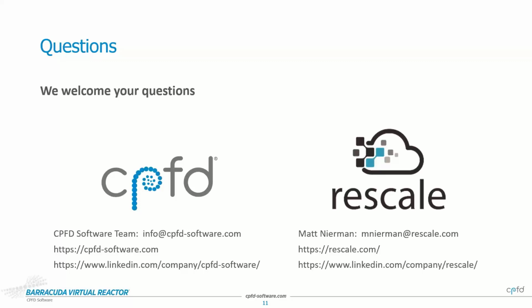Can I use Rescale or use the cloud alongside my on-premise hardware? Yes, absolutely. As we learned today, you can prepare your jobs on your on-prem hardware, and then when you're ready to submit a large job, you can do it through the Rescale cloud. It's really just a web browser portal kind of thing. Upload files, everyone knows how to do that, and then the job setup is pretty much a wizard in itself. You just follow the three ingredients: input file, select the software, input the command, pick one hardware, and then you're done.